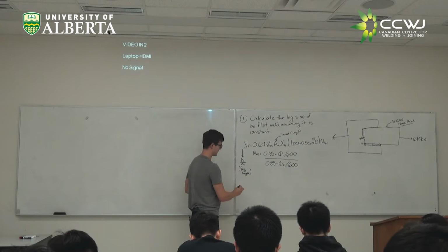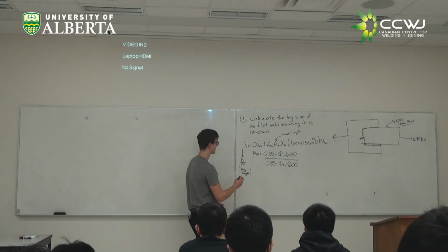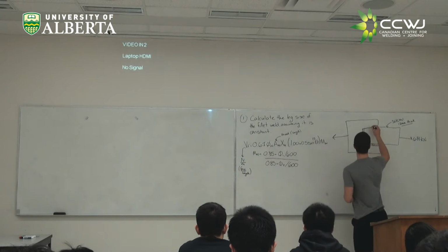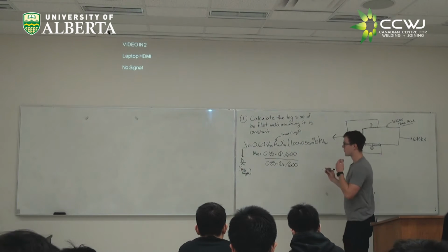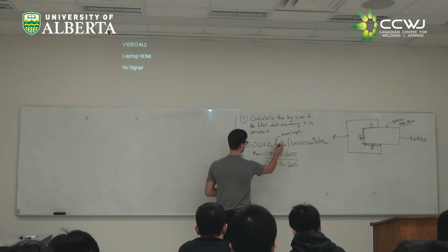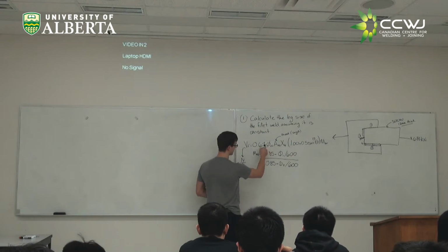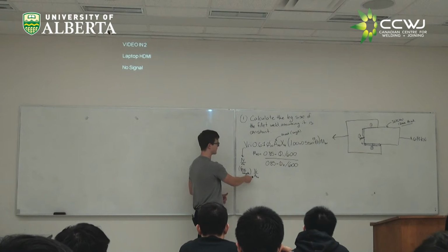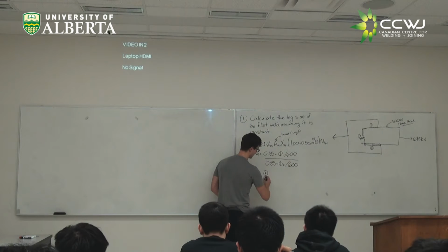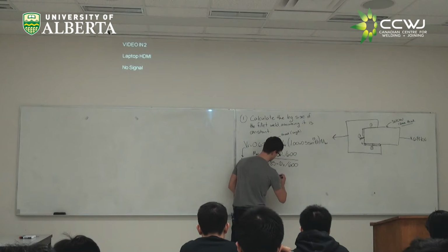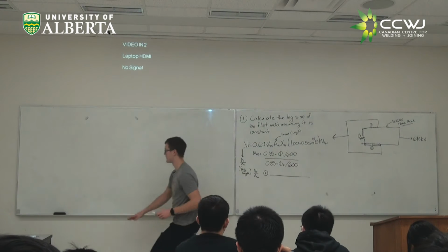We looked at solving this, I think, in the same example we went through quickly in class. If we have our welds, and we'll call these weld 1, weld 2, weld 3, what we're going to actually solve for, if we take this to the other side, is V_r over A_w, and we're going to calculate V_r over A_w for each of those welds. So if we start with weld 1, we're going to make a little table here. Actually, let's see, I'm going to do it over here so we get lots of space.